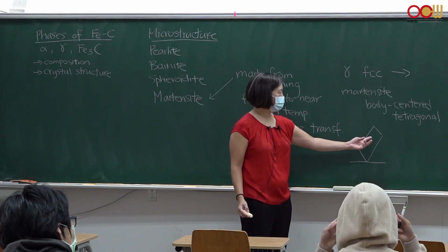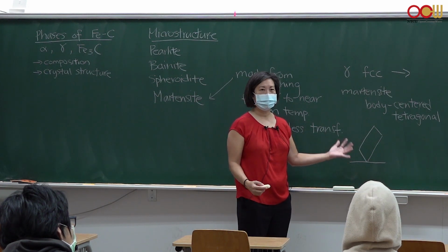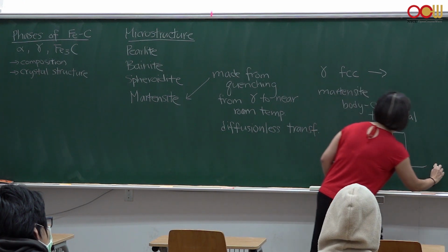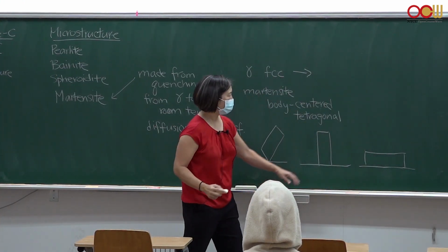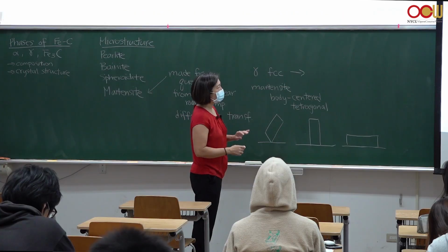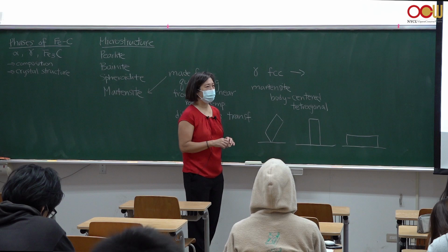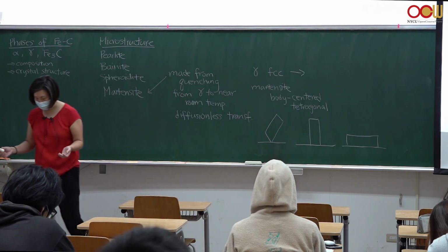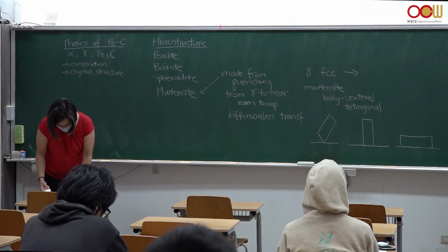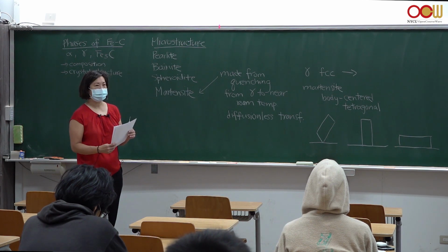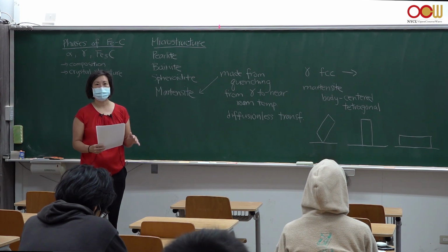Austenite at low temperatures would be this. It's not stable at all. It wants to do something else. Martensite would be like this, and ferrite would be like that. So Martensite is another microstructure that can happen with the material, and it is formed by quickly cooling. And it is not the most stable, so you're not going to find it on a phase diagram.